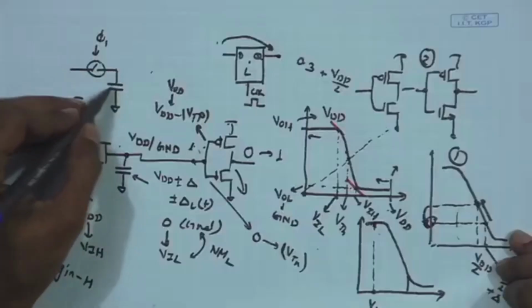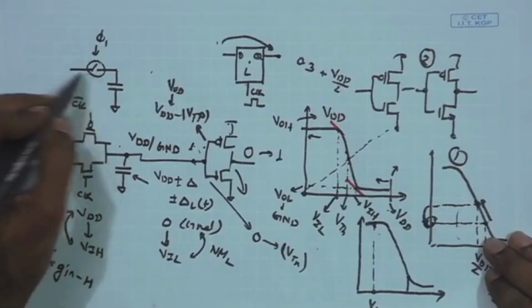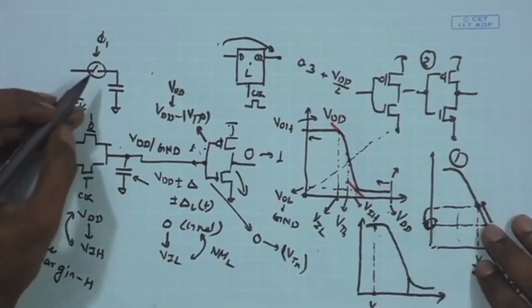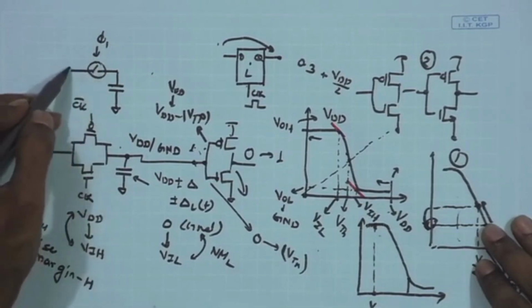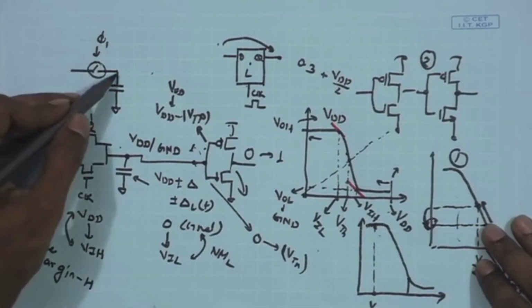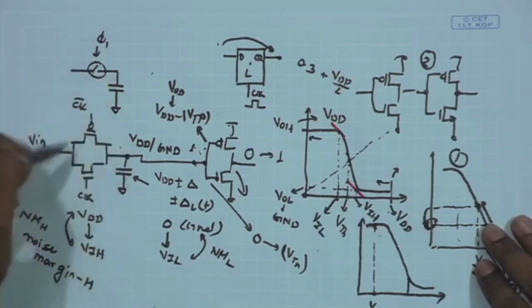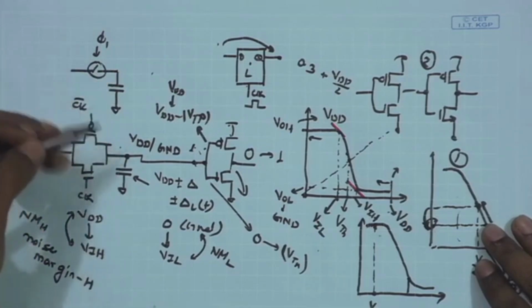Welcome back. Let us resume our discussion on the latch circuit that we are looking at, the transistor level implementation of the latch and the flip-flop. So, we started with the simplest latch circuit, which is just a switch along with the capacitor, and this can fairly well act like a simple latch. When phi 1 is on, or the switch is on, the input level VDD or ground will be sampled onto the capacitor. So, this is a single latch, which is a level sensitive latch.